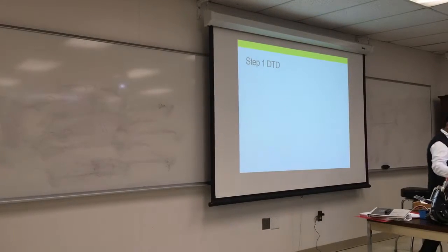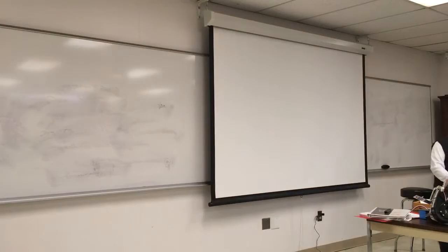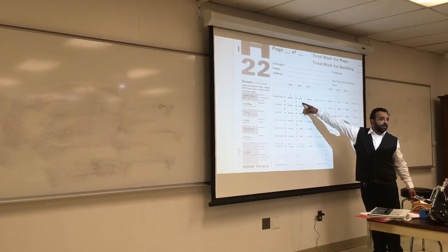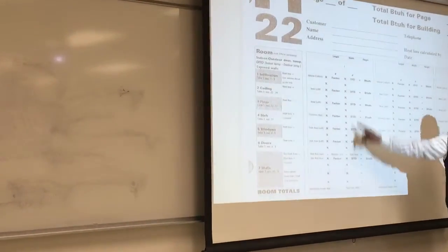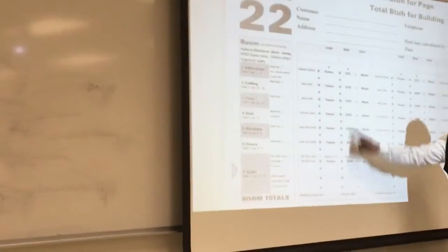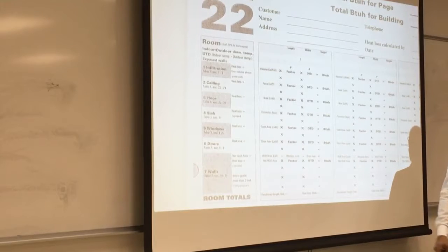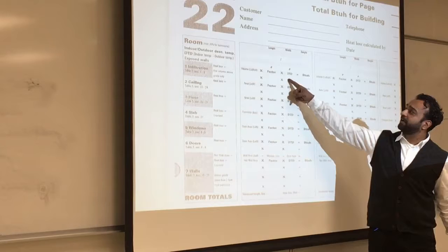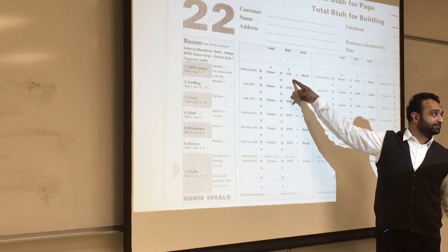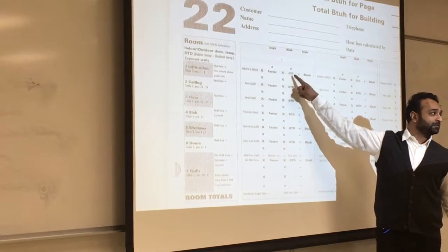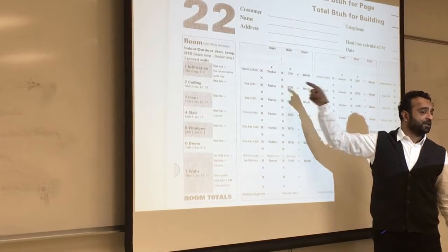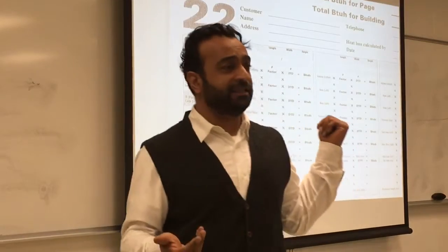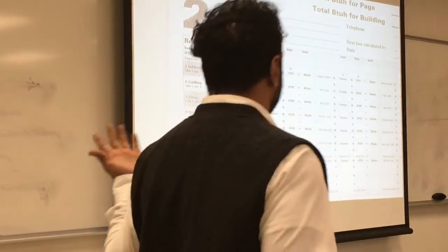And what does it look like in the sheet? This is what it looks like. And it's going to be the same for the entire project. Copy and paste all this all along. This is the design temperature difference. Design temperature difference: if you put the inside at 70 and the outside is 0, what is DTD? 70. And so on and so forth.